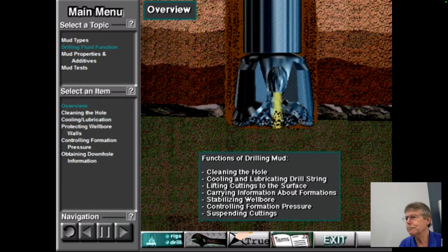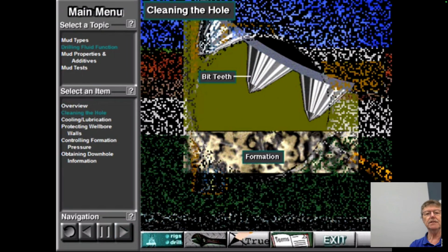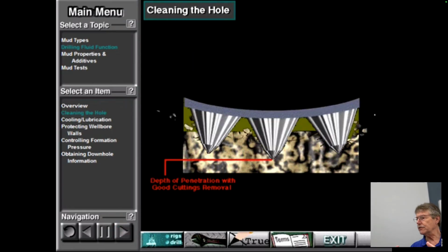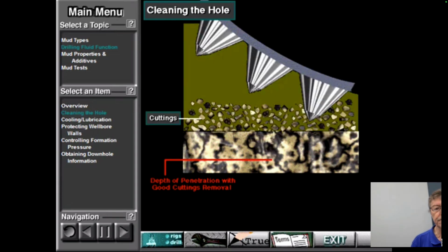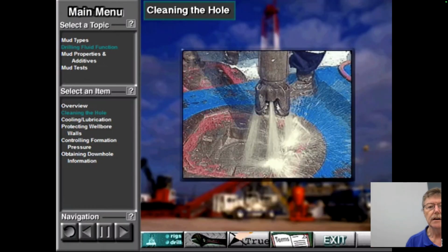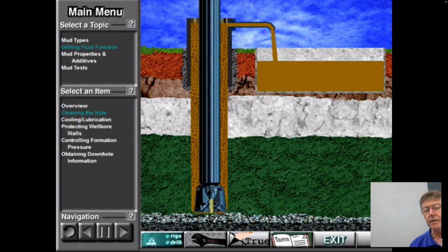Someone asked why we measure pressures, why do we care? Lots of reasons. For those of you who are environmental systems engineers, mining engineers, petroleum engineers, drilling holes in the ground, you have to balance the fluid pressures outside the hole with the mud weight in the hole as you go on. That's a big part of drilling. You can estimate that by the depth you are below surface, measure pressures in the reservoir, and from the height of mud, which is bentonite water slurry in the hole, you can calculate what it would be at the bottom of the column to balance what's going on in the bottom of the hole against that.